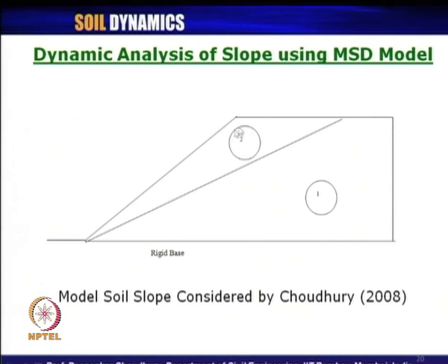So, this zone marked with number 2 is nothing but the failure zone of the soil, that is the slope which is failing at the condition of limit equilibrium we are applying, and this zone 1 is the static zone which is not failing. Truly speaking, it is not failing, I should say. This is the failing zone, this is the not failing zone. However, at far distance there is no effect of this earthquake or dynamic load. So, this is again the zone of influence which we need to find out by method of trial and error.